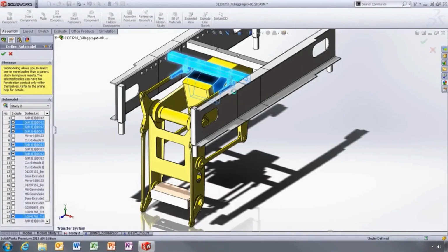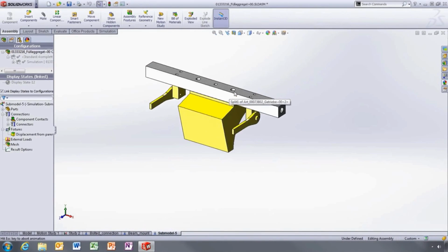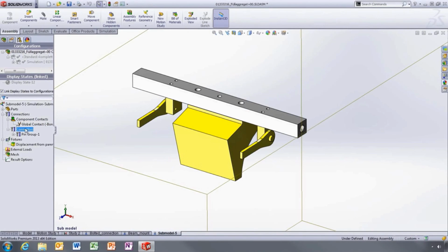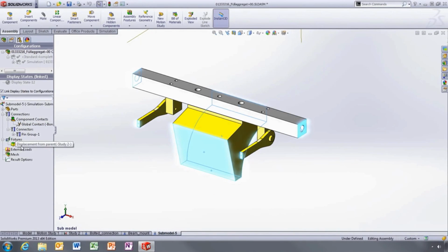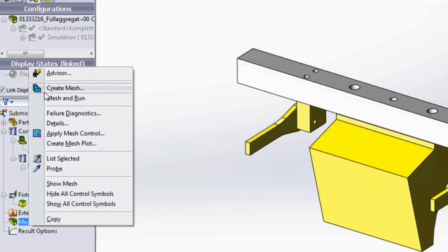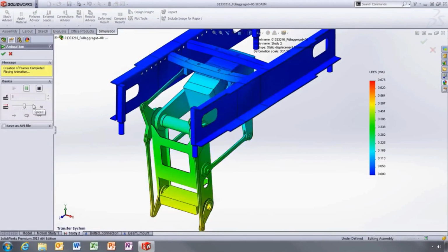Now, those pieces have to be bonded to the other pieces so then it can transfer the boundary conditions from the master assembly. So now, of course, what I can do is crank up that mesh and make sure that I'm getting converged results on just these critical response pieces. It saves me a lot of time because now I can crank up the mesh and just solve and iterate on either a mesh convergence study or some design geometry right on that small piece where I know the critical response is instead of at the entire assembly.